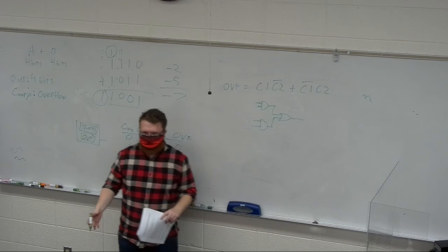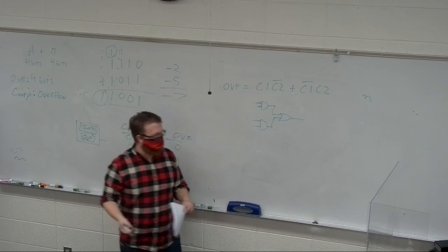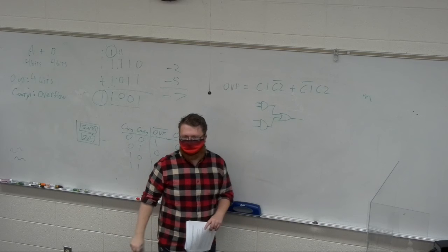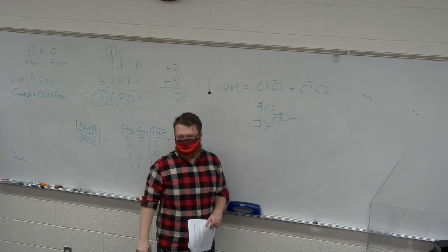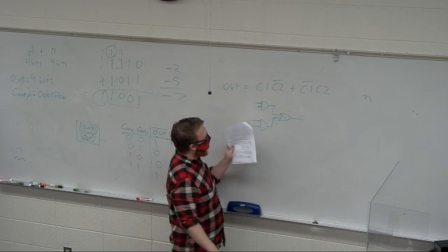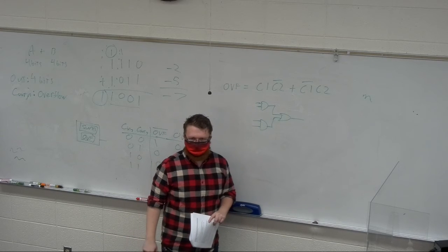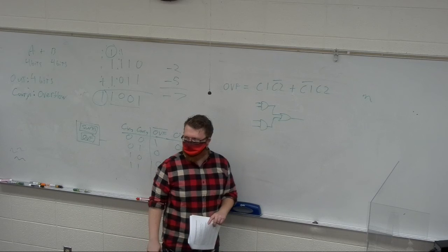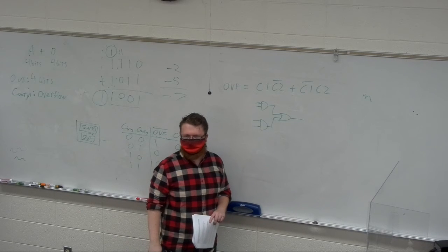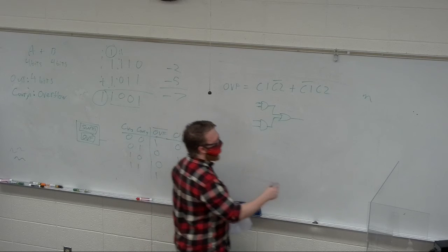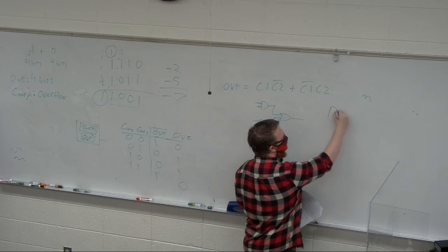XORs are not universal gates. They're not used as universal gates. This circuit is very easy to turn into just NAND gates. Have we done gate conversion in this class? I really don't remember. No. So the general idea is this is a NAND gate.